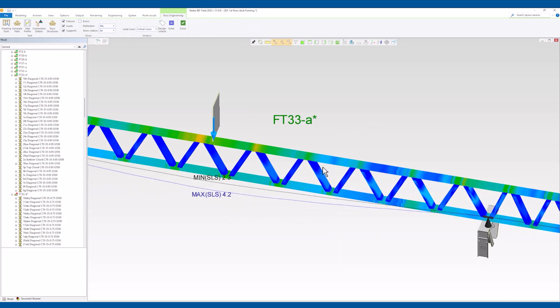Okay, the label turns green and the design passed. And from the bottom, we can actually see the capacity now reduced to 76.2%, which means actually increasing the material thickness from 0.75 to 0.95. In this case, I think it increases the capacity of the truss by 20% or more.